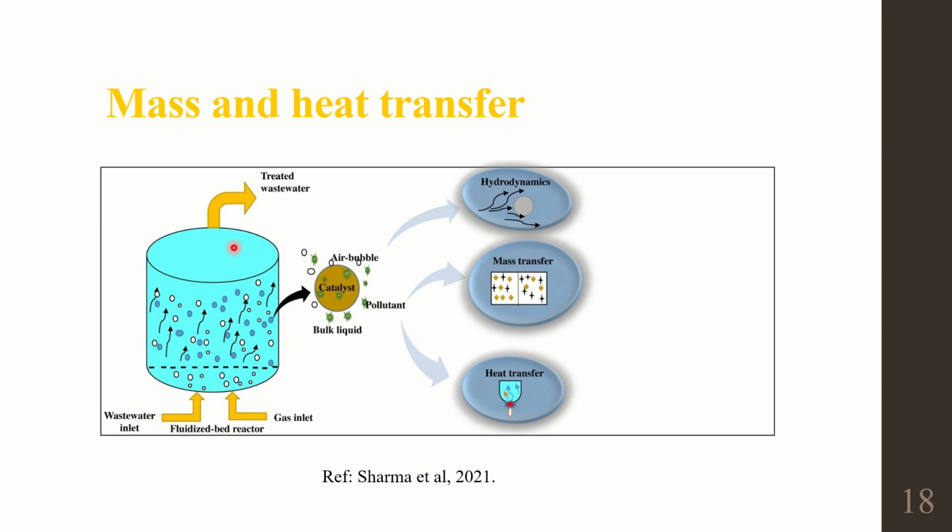That happens by means of these three factors. The first one is diffusion. When we are dealing with fluidized beds, where solids and gas are there, in some cases mass transfer takes place by the gas diffusing into the solids. That is what we call diffusion.